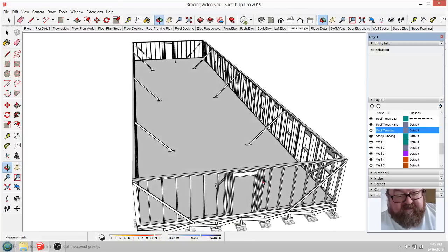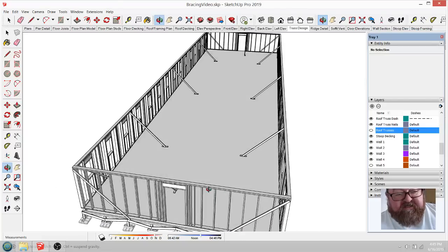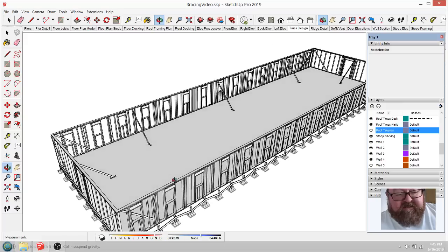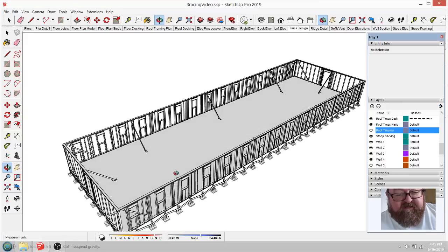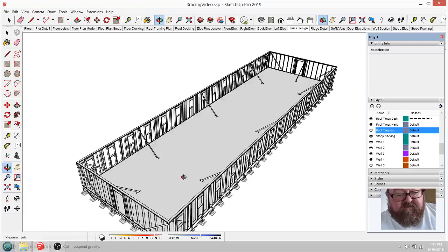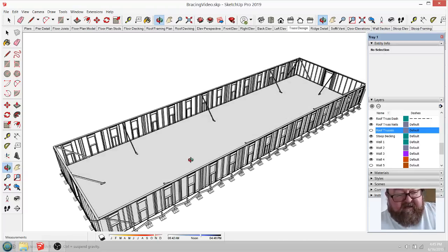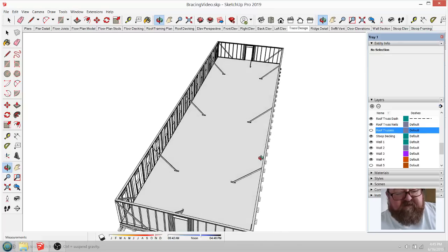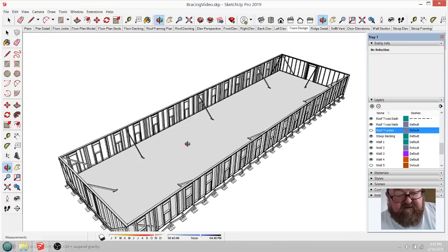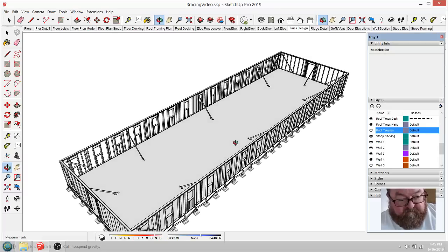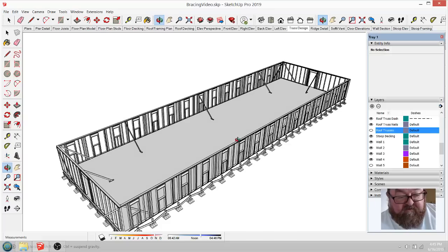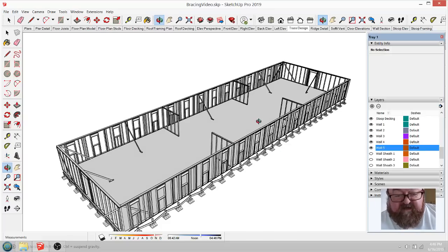So we're trying to work through this in a systematic way, and if you had an open building, this would be the minimal. Really, a couple of extra braces wouldn't hurt anything. The reason I'm only showing this many braces right now is because the next subject I'm going to speak about is shear walls, and to provide the proper resistance to shear, you would need our walls type 5.